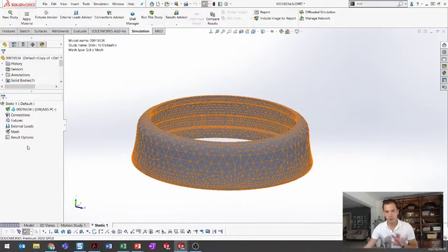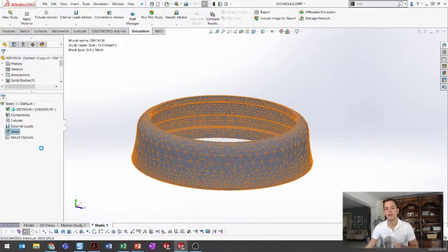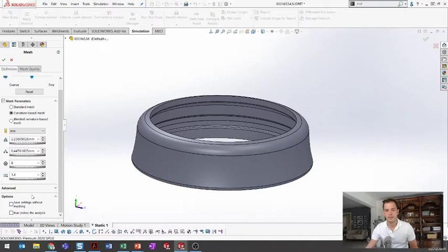So how do I switch between high quality and draft quality elements? Well, first, the old way. The old way is to, right here under Create Mesh, scroll down to the very bottom of your mesh box and hit Advanced.